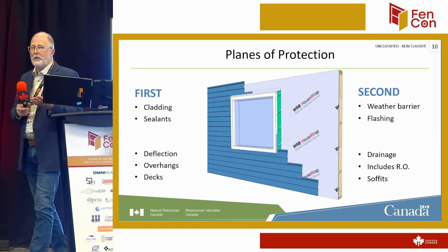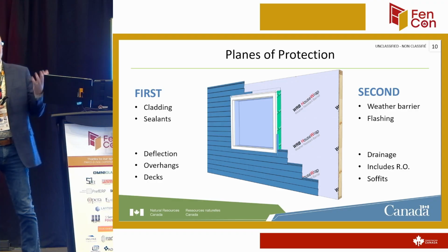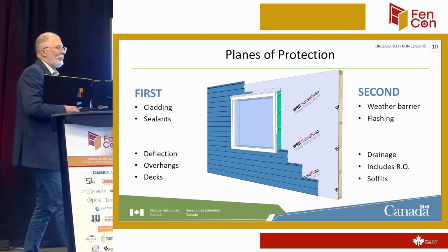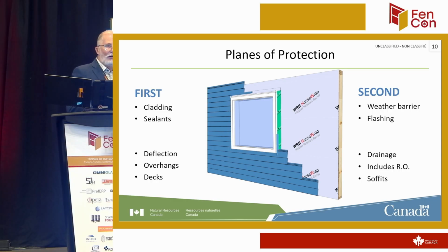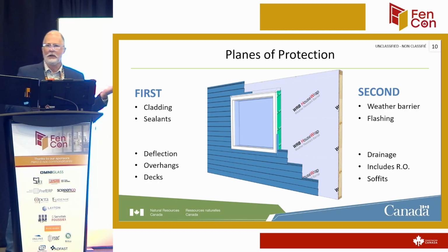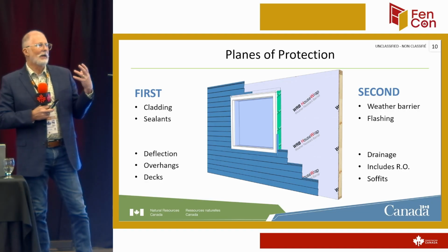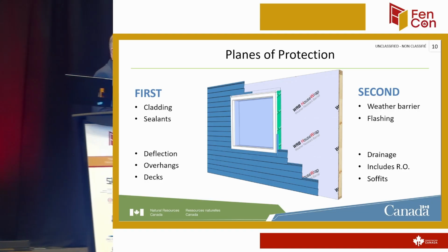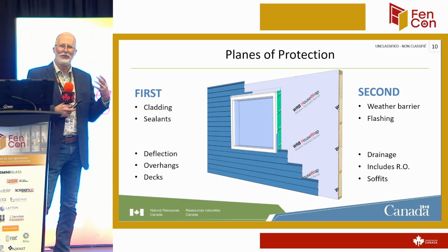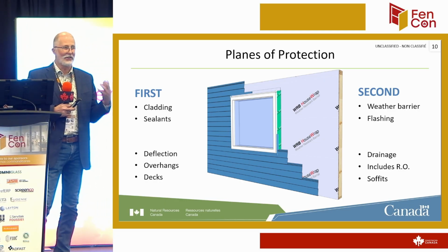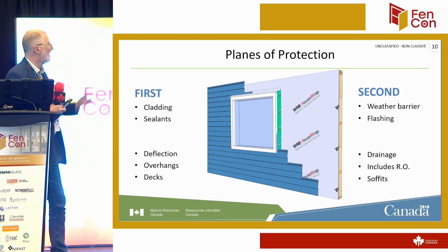Maybe you want to go to a vapor-permeable peel and stick. Maybe you want to go to just straight tar paper. Maybe you want a house wrap. There's only 1,000 house wraps to choose from, so you've got all sorts of options depending on what you want to do. The goal is, though, that it deflects water, but it's vapor permeable enough that the moisture that's behind it can dry back to the exterior. It's kind of like wearing a cotton t-shirt in the summertime, right? Remember the old polyester shirts? I'm thinking back when I was in the 70s, right? In high school, those polyester shirts in the summertime, you just sweat like crazy in those, right? But a cotton shirt lets all that moisture out. Same principle with what we're talking about here.